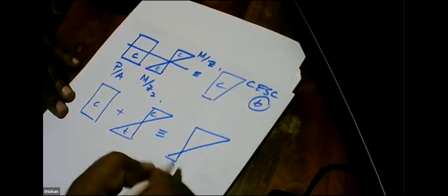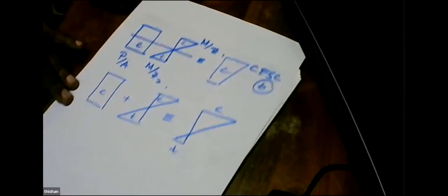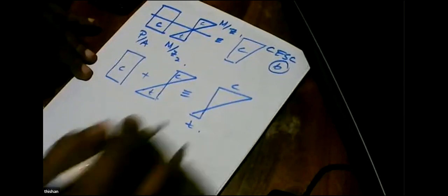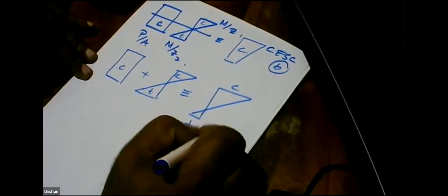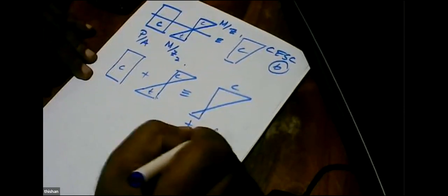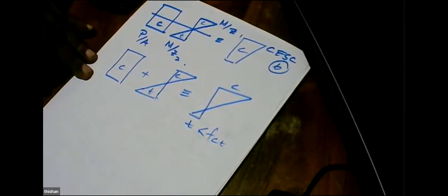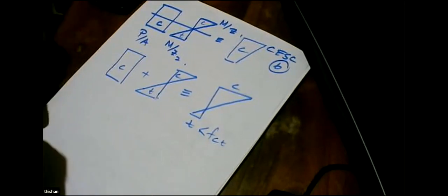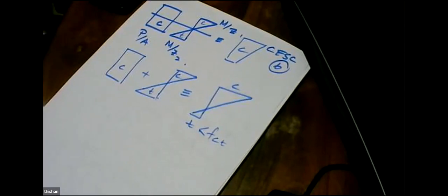So here you can limit the tension. That is also possible. And if this is less than the tension capacity of concrete, we will not get a crack. But we'll have a situation where it's about to crack, but it's not cracked. It's about to crack because the stress is very, very small. It's about to crack, but it's not cracked, right? So it's also okay.